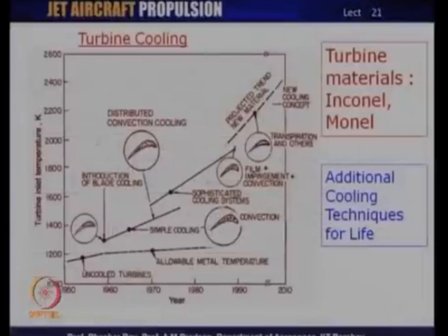Now, let us take a look at various kinds of cooling mechanisms that are normally used in aircraft gas turbine cooling. You see, the gas turbines in aircraft typically are subject to very high temperature. In fact, as we have noted before, thermodynamics clearly states that if you have higher and higher entry temperature to the turbine, you get more and more work extraction possibility. You also, of course, get a higher cycle efficiency or engine efficiency, reflected in the fuel efficiency.